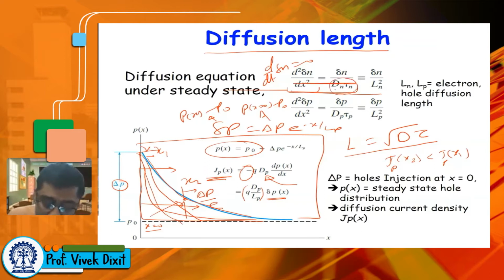You can put τ equal to infinite. So what will happen? This will become basically 0, right? So d²/dx² is 0, right? So that means you will have a flat line, or you will have some linear line, because the double derivative is 0, so the derivative will be constant. So your Δn will be some ax plus b type of thing, right?